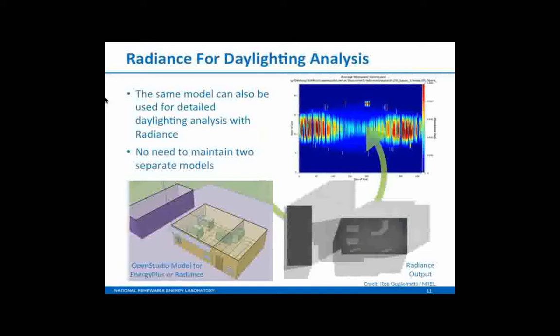So the idea here was, well, let's use Radiance for what it's good at, EnergyPlus for what it's good at, merge those results through EnergyPlus, through OpenStudio, again, programmatically, to give you sort of an integrated building model result. Because Radiance has different capabilities than EnergyPlus, that implies that the OpenStudio model, which sort of sits on top of all of these other building models, the EnergyPlus model, the Radiance model, et cetera, has to have the capability to speak Radiance or to speak EnergyPlus, right?